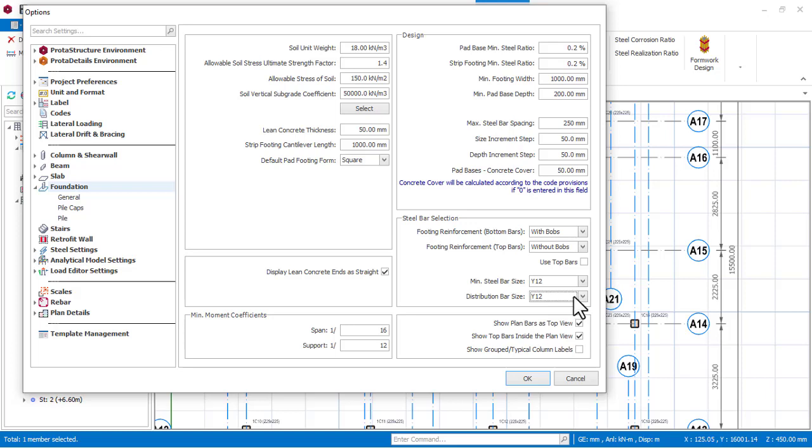Or even if it's a 1-story building and it's very, very large and has much live load and dead load and much design load, then you can choose 16. But even if you choose 12 and it is now required to use 16, you will see along the line on the design the warning that the steel is not sufficient.